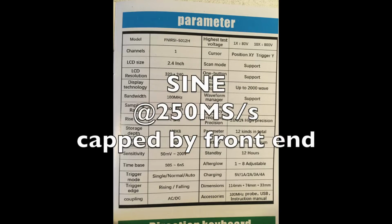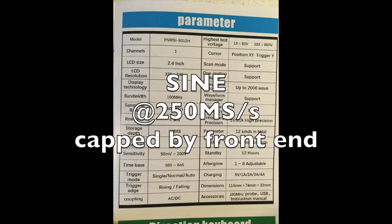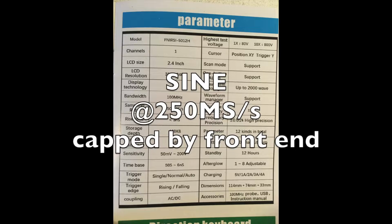And at 250 megasamples a second with a sine wave, the Nyquist frequency is 125, so we're capped by the front end, theoretically. And if you have the probe, you're never going to get there anyway because you're limited to 70 megahertz. Visual demonstration time. Now, let's see what that looks like, as in losing upper harmonics and rounding our square wave off to a sine and then losing amplitude.